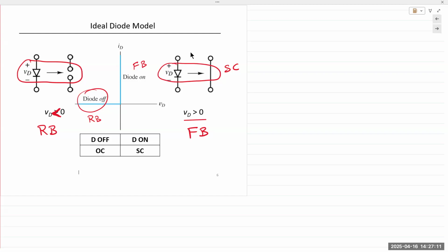Then we added another diode circuit, and the operating principle is still the same, but now it was connected in the opposite direction. It doesn't matter whether it's connected opposite or not. It's in the opposite direction simply because we wanted negative operation. So the cathode was connected; when the output voltage goes negative, the diode turns on and the capacitor is able to charge. When the output goes positive, the diode is off, the circuit gets cut off, and the capacitor has no pathway to discharge. So that's a quick and straightforward way to analyze using the ideal diode model.